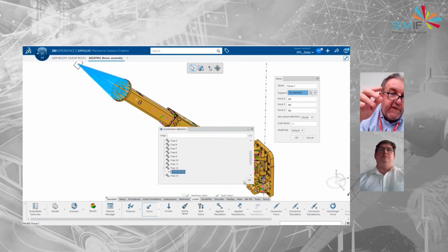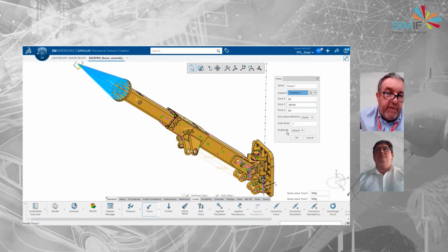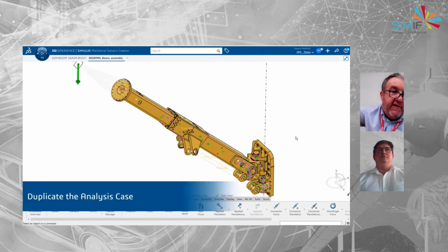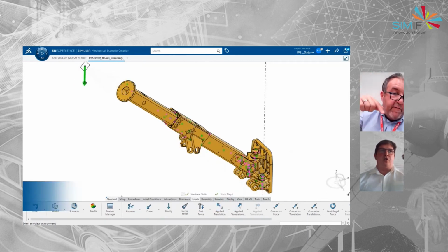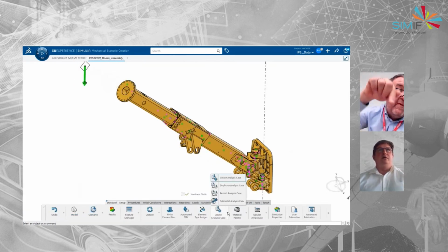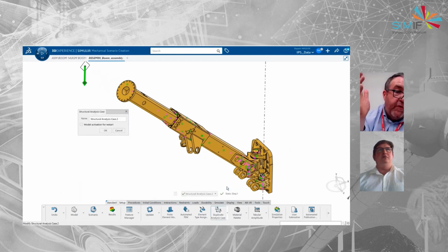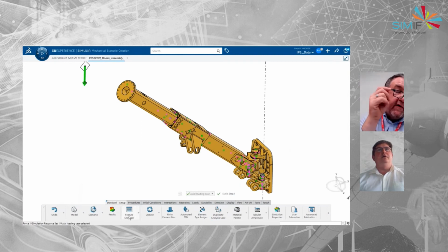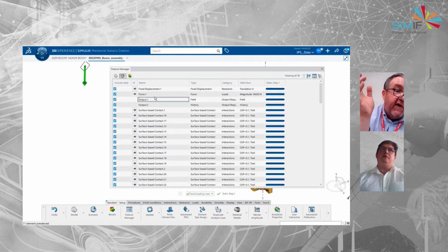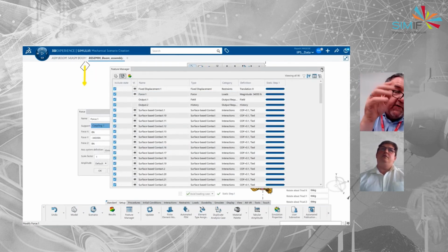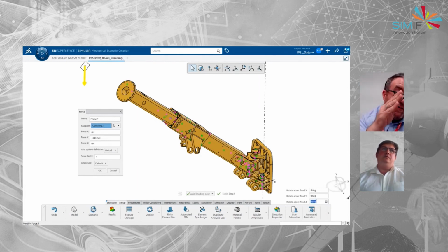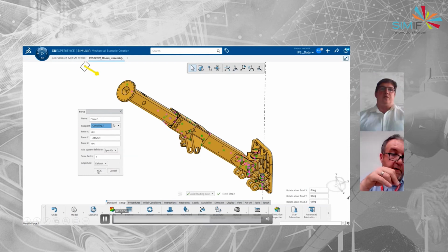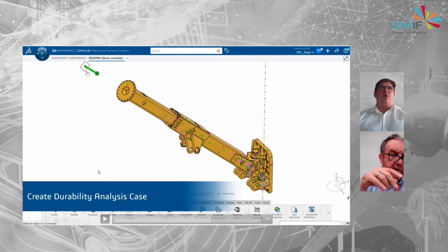So I can see all the forces that are going to be applied to the coupling, to where the arm is, the machine at the end of the arm there. That one's going straight down, but there may be one applied straight down the boom arm itself. And if you've got any moving parts that are going to oscillate, like a drill, we may want to define that, because we're looking at the fatigue life of this particular part as well. So far we've applied one load going straight down, and one down the arm.